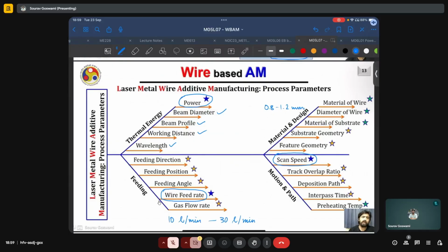Compare that to the temperature of the substrate, which will be at the ambient temperature, say 24 degrees Celsius, while the metal will be at some 1400 degrees Celsius, which presents a very large thermal gradient for the metal. And these large thermal gradients can result in residual stresses. By preheating the substrate to some pre-decided temperatures, say 200 or 300 degrees Celsius, we can reduce the magnitude of the thermal gradient, which can prevent or mitigate the formation of residual stresses, or at least moderate them.